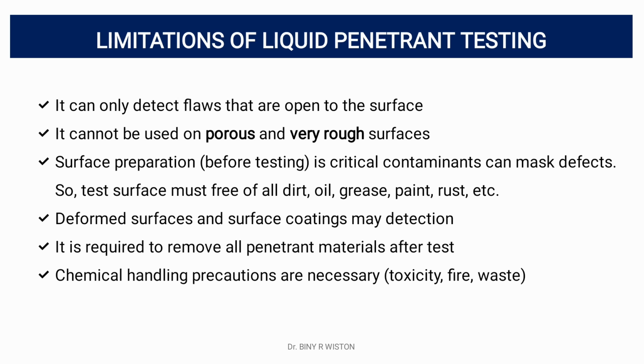Surface preparation. The effectiveness of LPT relies heavily on the cleanliness of the surface. Contaminants such as oil, dirt, or paint can interfere with the penetrant's ability to enter defects, leading to false negatives.